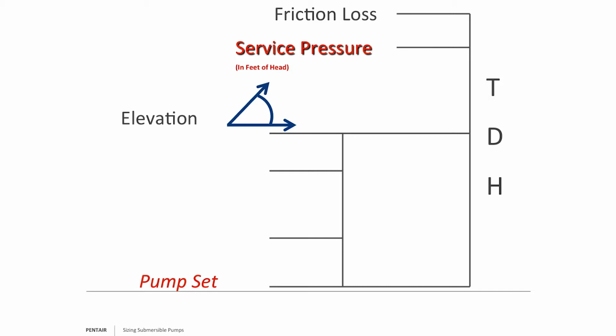If, for example, in this later example I'm showing you, we'll have 0 feet of elevation, and I do that in the example because I want to make it simple and clean and quick for this webinar. But we have 2 branches in that system. One that goes to the left, one that goes to the right, or as you would see it, one that goes to the top, one that goes to the bottom of the screen. If the one that goes to the bottom of the screen is at 0 feet of elevation, and the one that goes to the top of the screen actually goes down 60 feet, its farthest head would be 60 feet below rise. Do I worry about that?